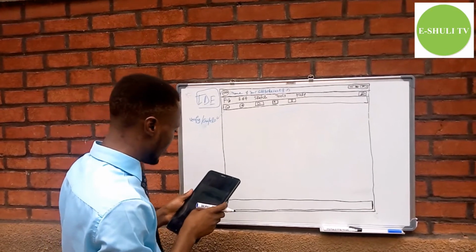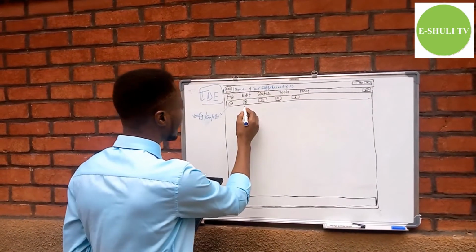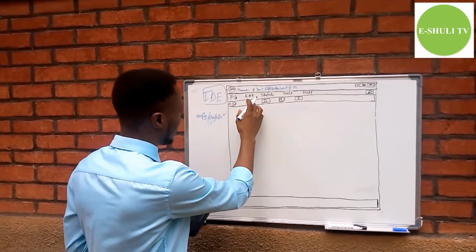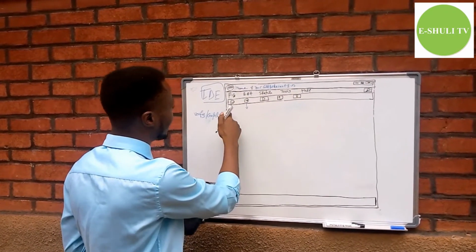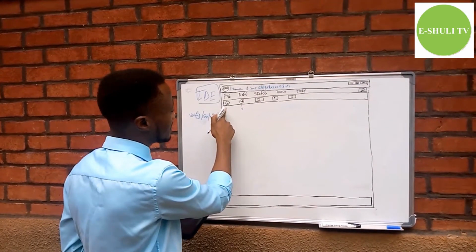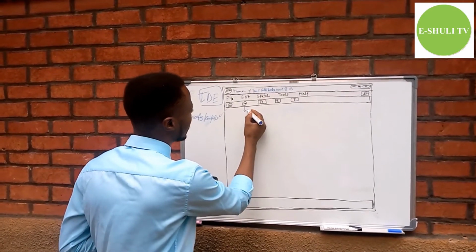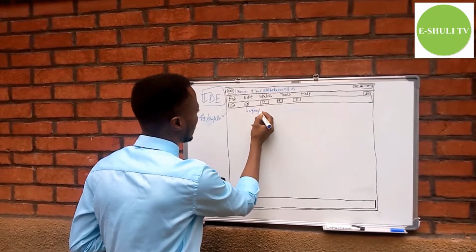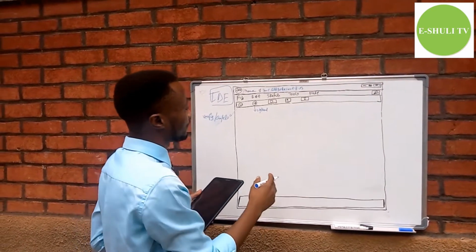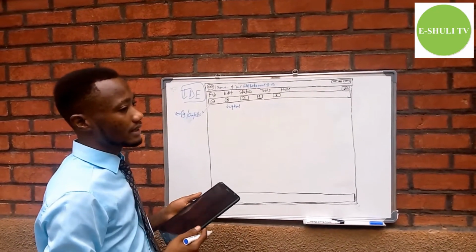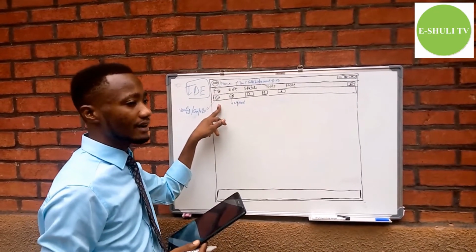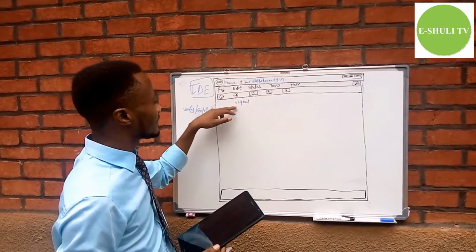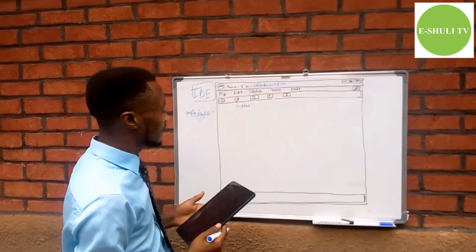Then this one, you click on this button after verify or compile your codes, to upload your code into Arduino. If you finish to build your codes, the first step is to verify or compile if there is no error. Then the next is to upload to your Arduino board.